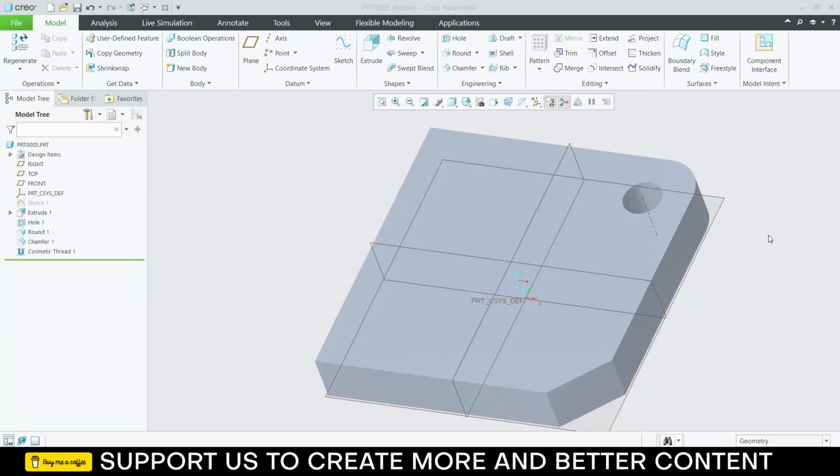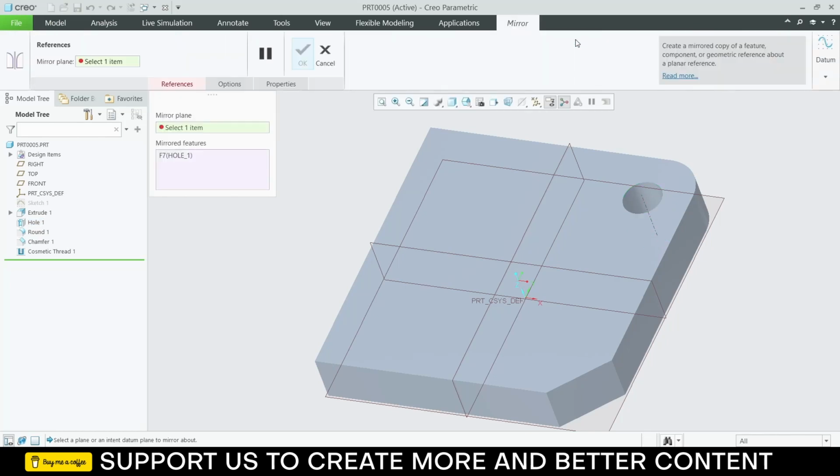Namaste. In this video, we are going to learn about the mirror command. How can I use mirror? For example, if I select this feature, notice that the mirror is not highlighted. So how can I use it? Don't select the feature from here. Select the feature from the model tree. Select this. Notice my mirror command is highlighted. So click on the mirror. Now it is asking for a plane about which you want to mirror.